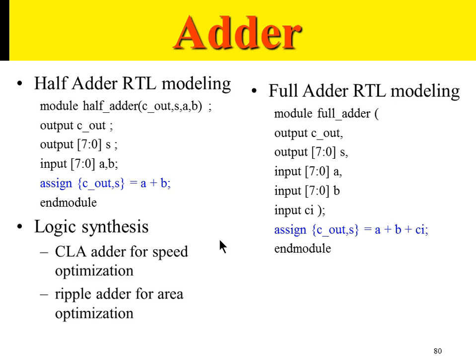When you do hardware design, you normally do something called optimization of the design. That optimization is done automatically using the synthesis software. And when you optimize the design, you have two options. You do optimization for area, or you do optimization for timing.